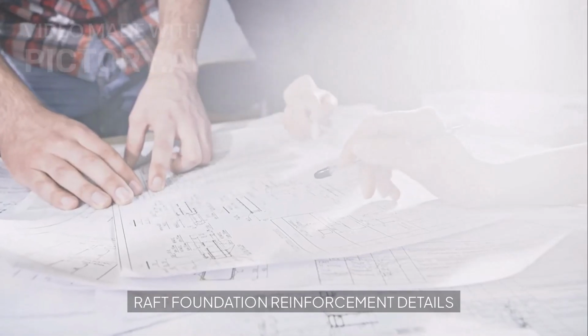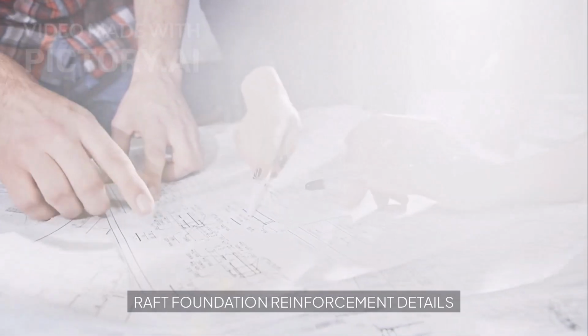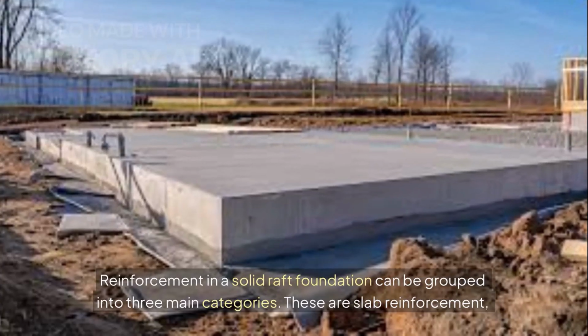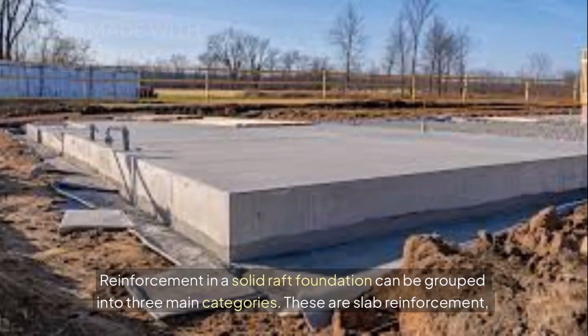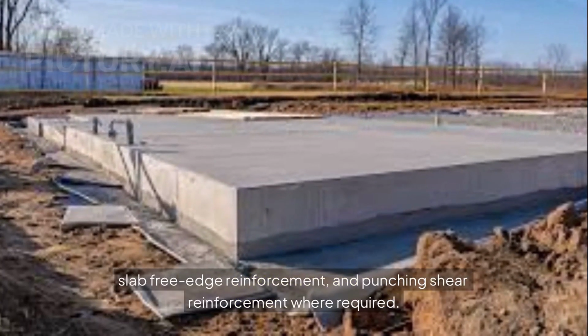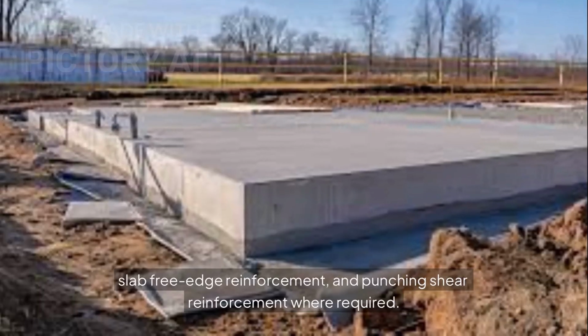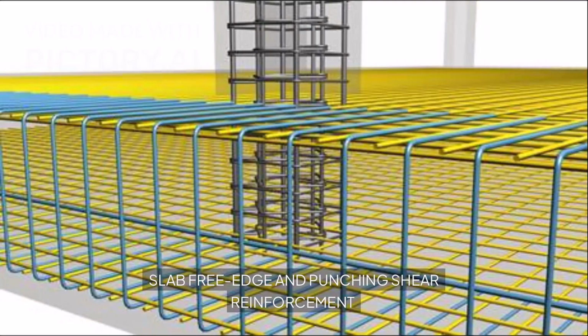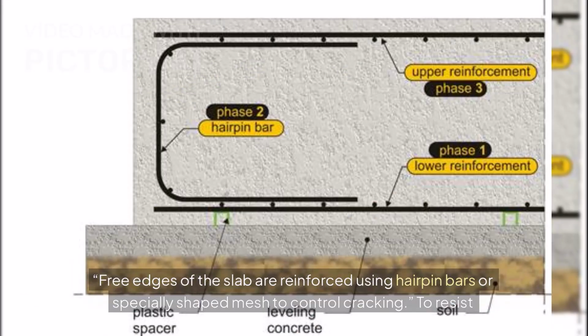Raft foundation reinforcement details. Reinforcement in a solid raft foundation can be grouped into three main categories. These are slab reinforcement, slab free edge reinforcement, and punching shear reinforcement where required. Slab free edge and punching shear reinforcement. Free edges of the slab are reinforced using hairpin bars or specially shaped mesh to control cracking.